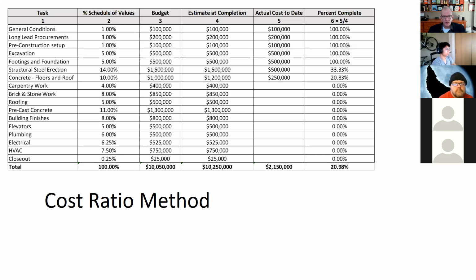Now, most contractors are going to try to have higher percentages towards the beginning of the project and smaller percentages towards the end of the project. That's human nature with contractors, because if excavation really is costing 4%, it's nice if I can get 5 or 6%, because that gives me more of the money owing. So I'm ahead.